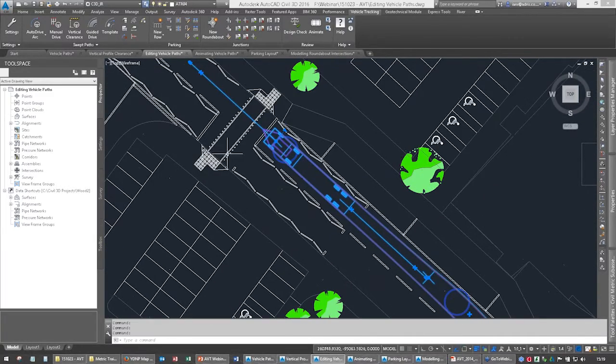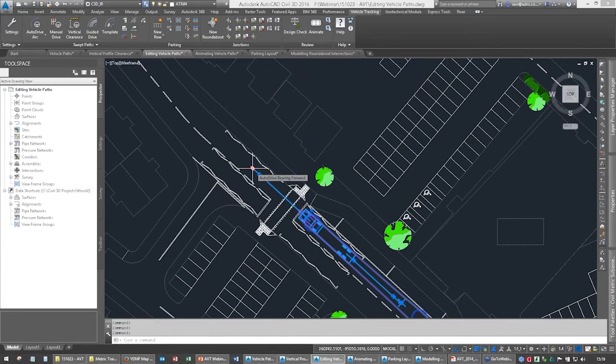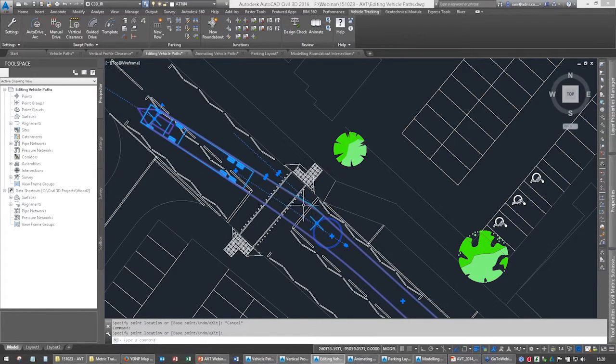So that's my truck. The one thing that I just wanted to show you in the editing, this one here, this grip here, this is a bearing forward. So what I can do here is I can start continuing but using the bearing tool. So now you can see it's saying, right, this is going to be the bearing of the truck, so it's going to carry on in that direction. Whereas if I do an arc, watch what happens. Can you see the steering angle on it? It's changing. So bearing, it's going to just bear to that direction, and then it automates adding in the widening where the trailer will oversteer there. That's the wrong term, isn't it?